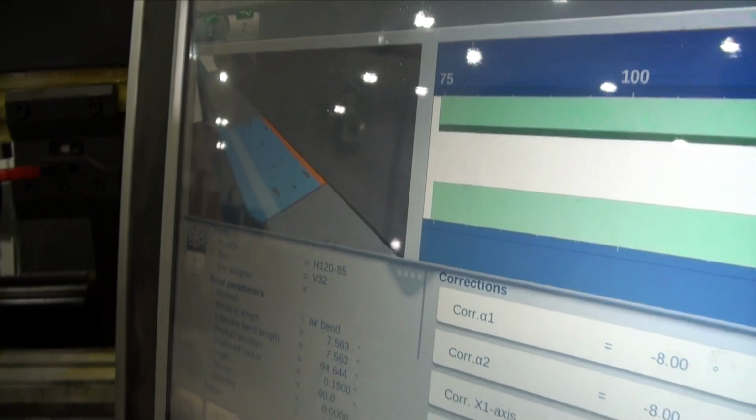So that's a quick overview. It's a quick overview on how to export and map layers in Solidworks, convert them over to use the same file to run it on the plate laser, take that same CNC file and have it import into your Delem controller, assign those bend values, and you'll have that product forever until you change it or edit it, and you're good to go. That's it.